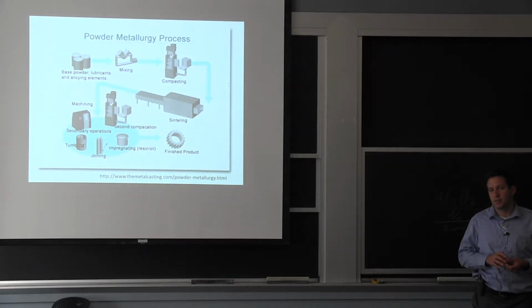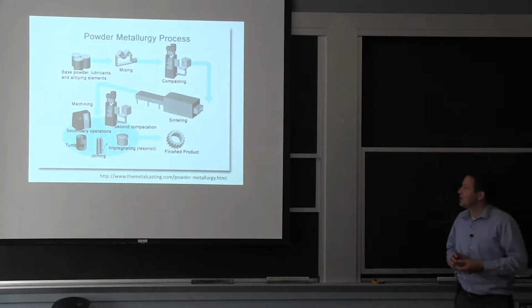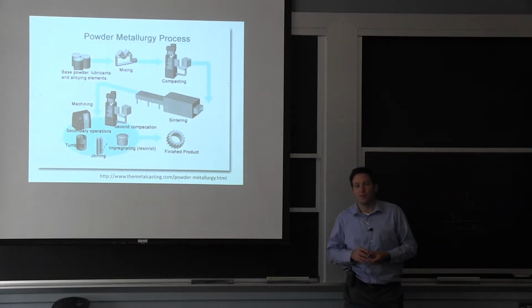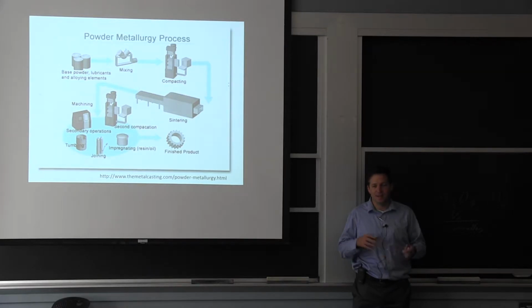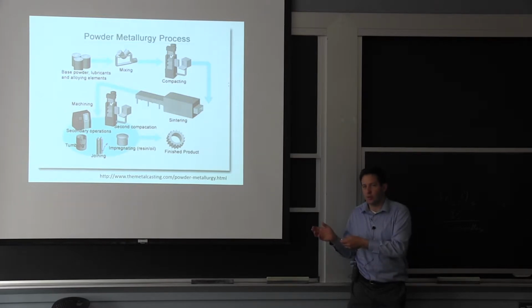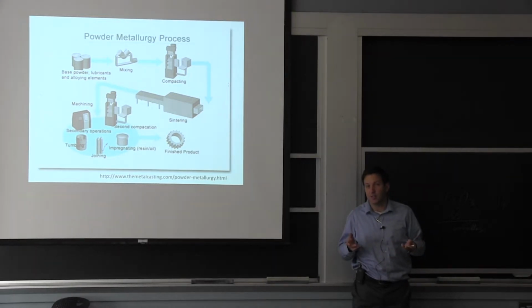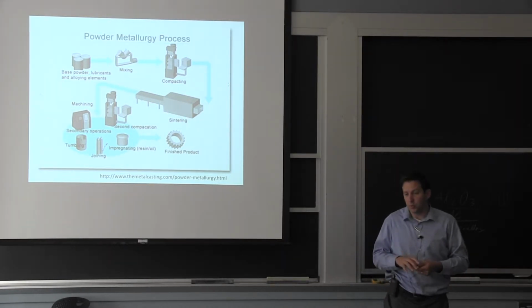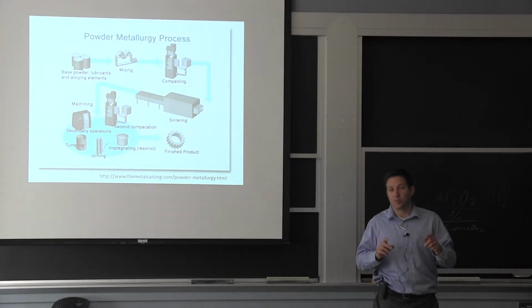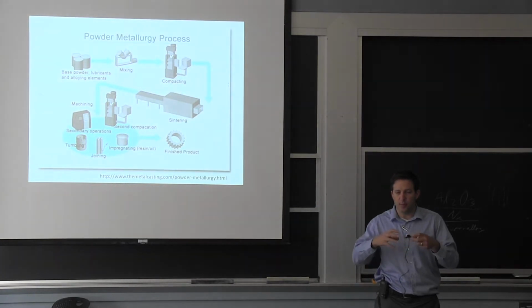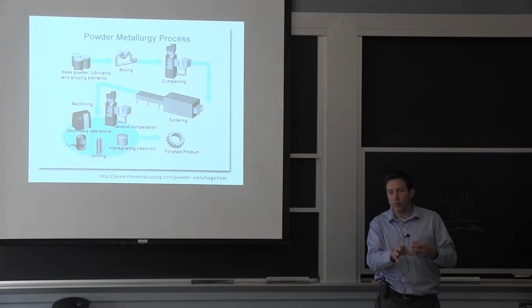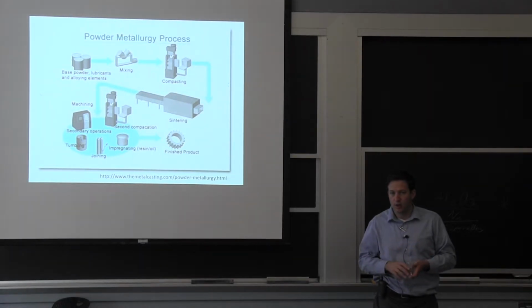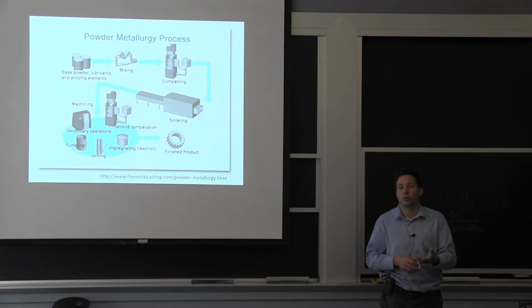Yes? Are the grain sizes going to be determined by? Your powder and the sintering. So there's this cool idea to make nano-grain powder to try to make nano-grain parts, but the problem is you're going to heat it up along the way. You can do it with what we call cold spray, which is kind of warm spray. You just heat up the powder hot enough that it's soft enough that it will deform and interlock with the previous layer on the substrate, but it's not as strong. And that's a way that you can maintain your original grain structure.